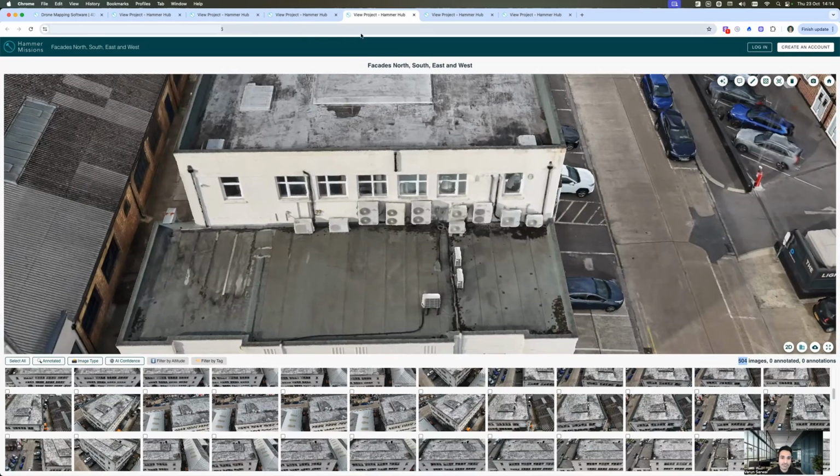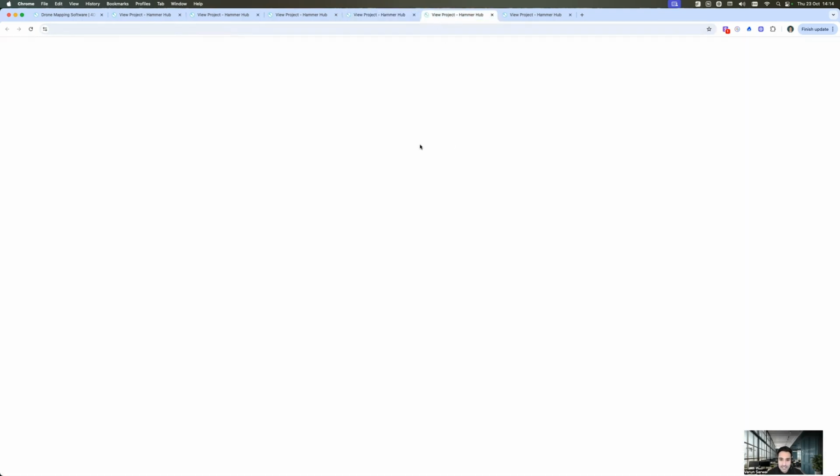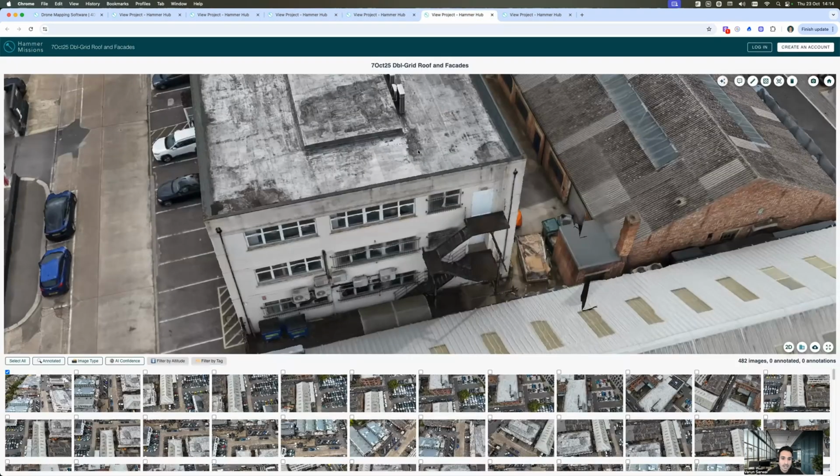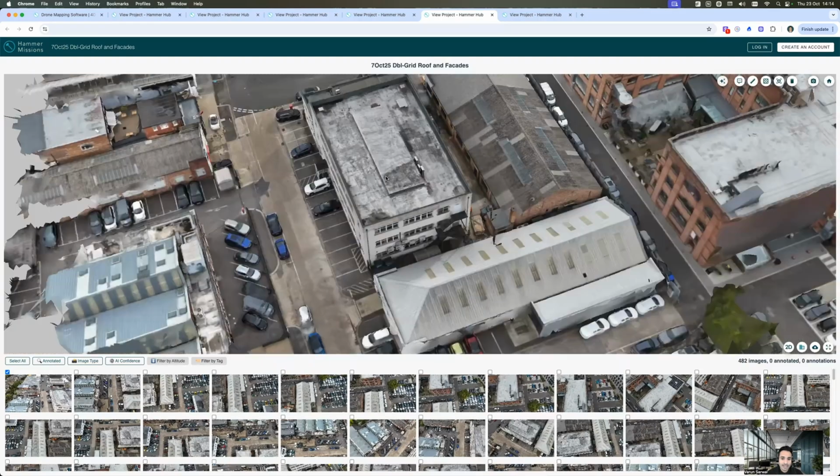Now, these were the first 4 flight plans. What happens if we now start combining those flight plans? So let's say we take the double grid flight plan from the single altitude flight plans, and we take the double grid looking into the building, and we combine it with the facade mapping. Ooh, drum roll, let's see what happens. So the first project is basically we've got our double mapping flight plan, and we've got facades added to it. So let's have a look at this.